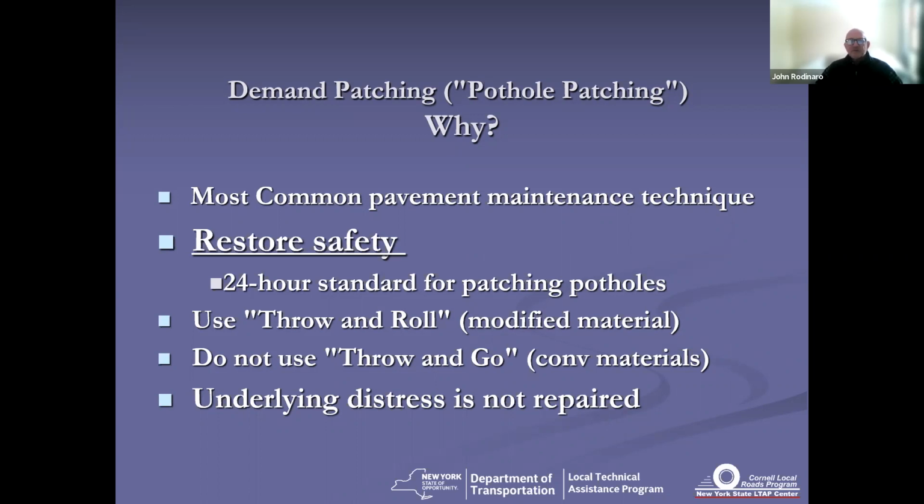So in terms of techniques, there are two particular techniques we're going to talk about. The one we want to focus on, the one we strongly recommend, is the throw and roll. You're going to be using modified materials most of the time, and we'll talk a little bit about why that's so important. We definitely strongly discourage you from using throw and go. It doesn't matter what material you're using, but primarily you'd be using conventional materials. We would strongly recommend you don't use that approach. And in all cases, your underlying distress is not repaired. You're going to need to make some permanent repairs when the weather gets better, when you get into the construction season.